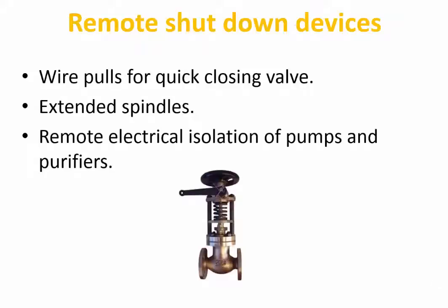Our remote quick closing valves, this is one similar to what you just saw on the Bluefin video. When they're in the open position, it winds up against this spring pressure, and if this lever is pulled through a wire onto the upper deck or above, then it will instantly close that valve. But it can be as simple as a ball valve, which will just have a wire pull which pulls 90 degrees to close.